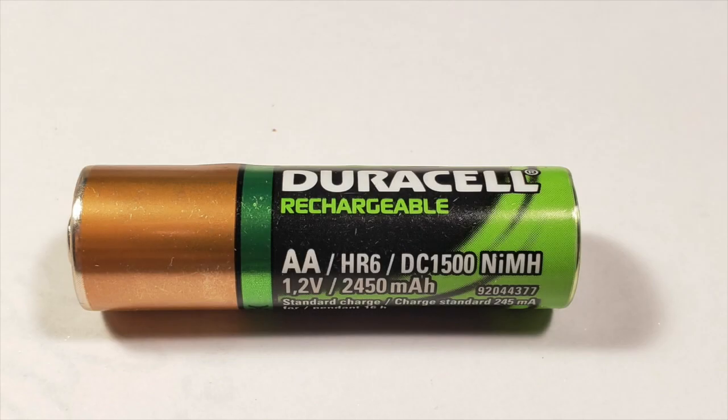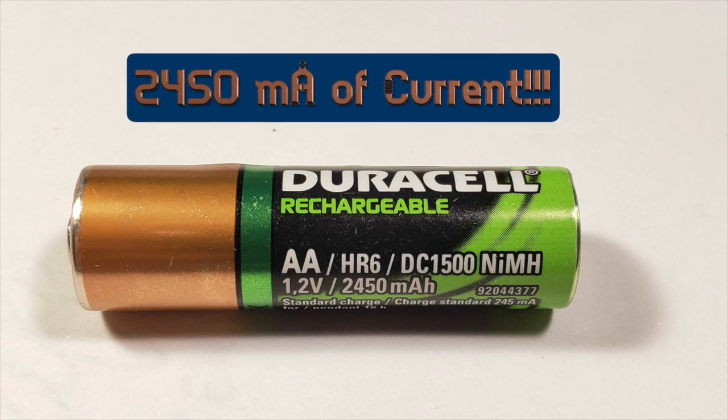So the last thing to talk about is the capacity of a battery. If you notice down here at the bottom, it says 2450 milliamp hours. What that means is if you were to have a device attached to this battery that drew 2,450 milliamps of power, it would only run for 1 hour.